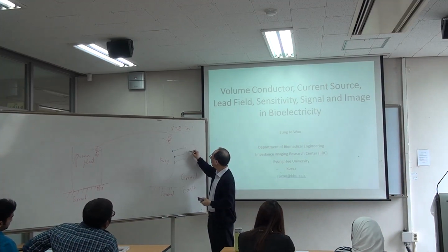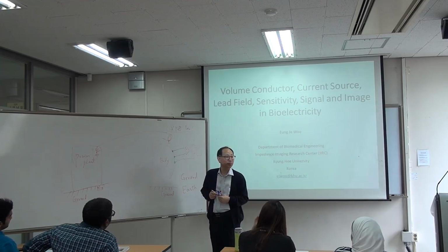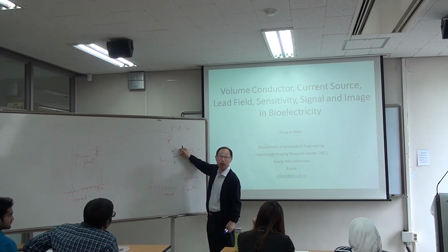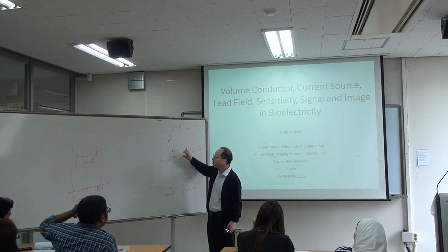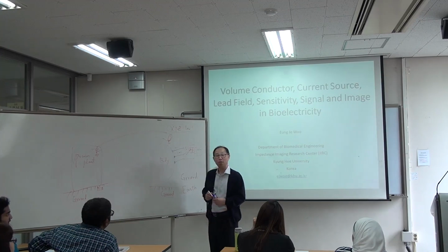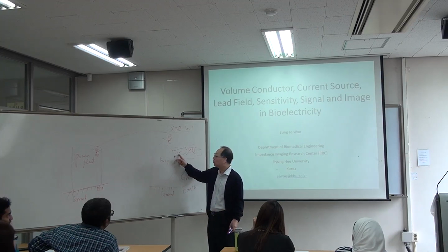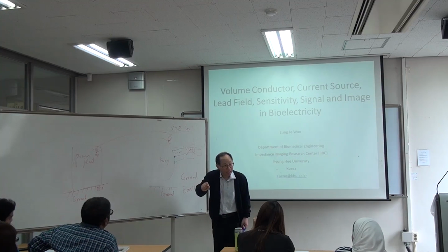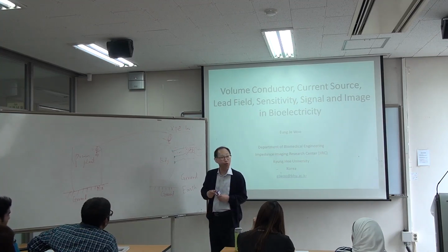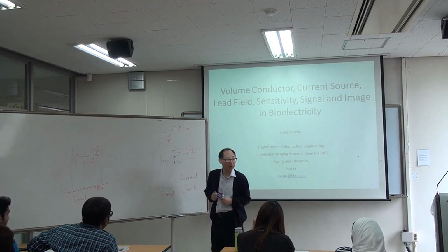we are going to measure voltage between these 2 points. And we are going to do A to D and microprocessor and display the voltage difference between these 2 points. So, this voltage is 1 millivolt. This voltage is 0.9 millivolt. When you say this, we have to specify a reference point, right? Since this body is not grounded, I'm just arbitrarily choosing this point as the reference point.